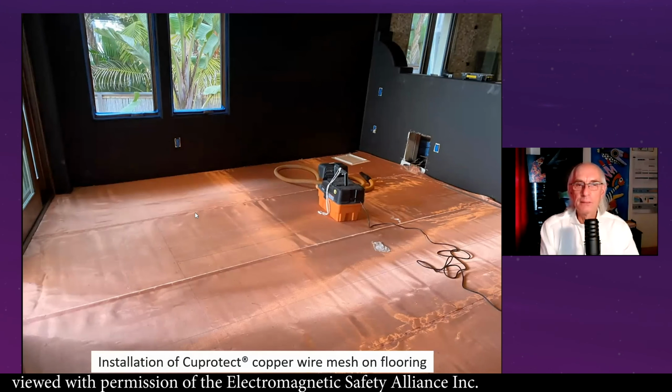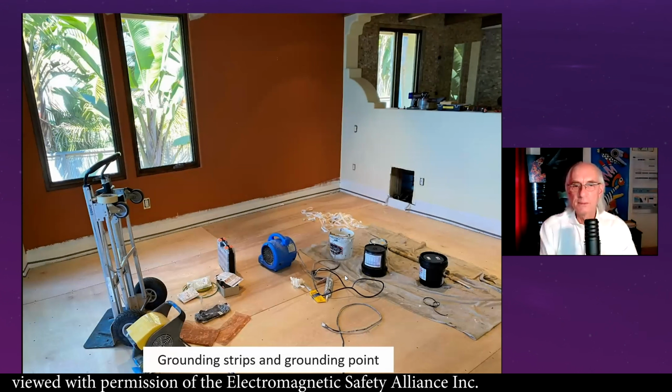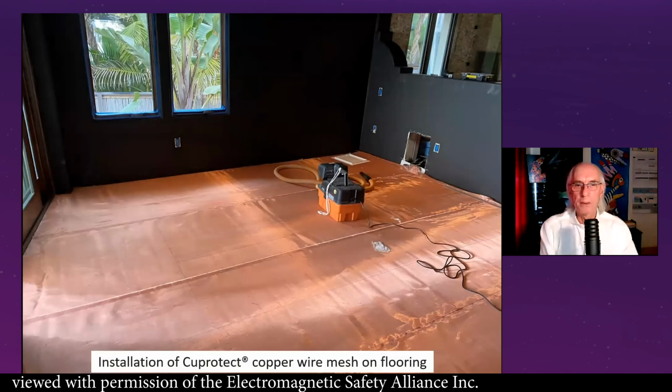Why do I use a copper wire mesh? Rather, why do I not paint the floor surfaces? For a very simple reason. If you look at it here, we've got seams in the wood, and the building is going to move and shake, and paint may crack or deteriorate, while a copper wire mesh is fairly flexible and is going to endure movements and not be destroyed or torn. So that's why we use a wire mesh.